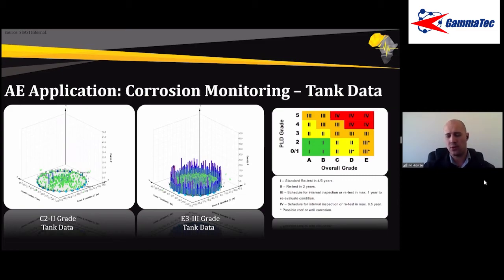If you were just to do a normal welding repair, even if you just load it the first time, you'll de-stress, you'll get settling, etc. So what we do is, if you have a welding repair in a vessel, we stress it, monitor it, you get a whole bunch of emissions from it. We then unload the vessel and take it up to just below the previous loading, and you should see almost no emissions from that vessel then, because all the stress has been relieved, and we can then evaluate if there's continued damage even after stress relief.